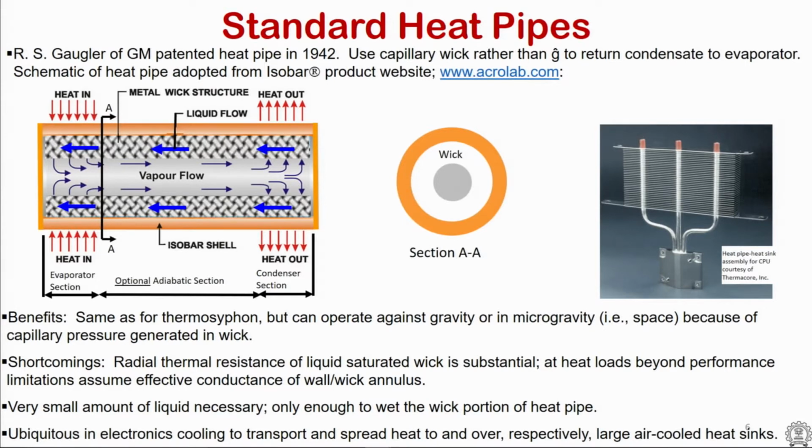So, there are two mechanisms that impact heat pipes. One is the vapor flow, which can depend on the operating temperatures and the fluxes. One can be limiting the operation of the heat pipe because the vapor is moving from evaporator to condenser, that is, it could be vapor transport limited or liquid transport back to the evaporator limiting.